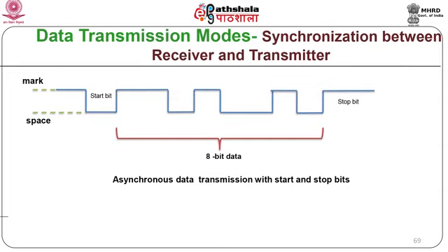It is an extremely reliable communication mode but a bit slow due to significant overhead caused by the addition of start and stop bits per character transmission, and is inefficient when large blocks and volume of data need to be transmitted.